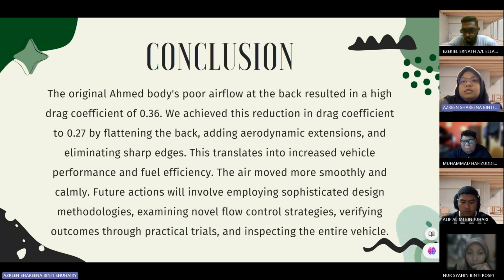For the conclusion, the original Ahmed body has very poor airflow, and the result is a high drag coefficient of 0.36. Then we achieved a reduction in drag coefficient to 0.27 by flattening the back, adding aerodynamic extension, and eliminating sharp edges.